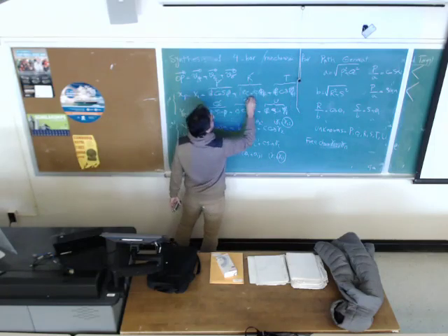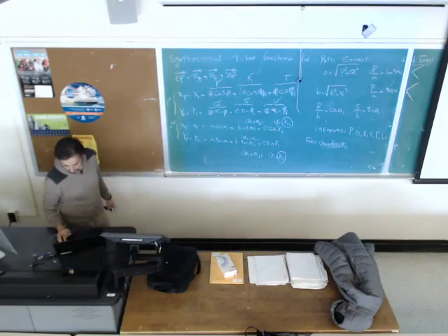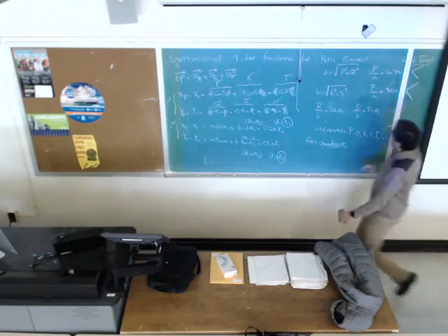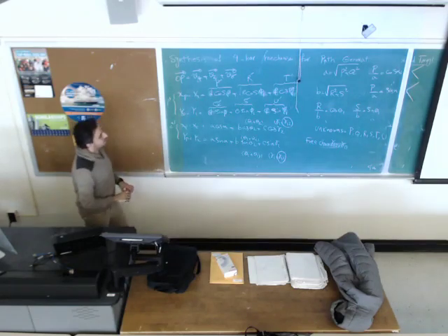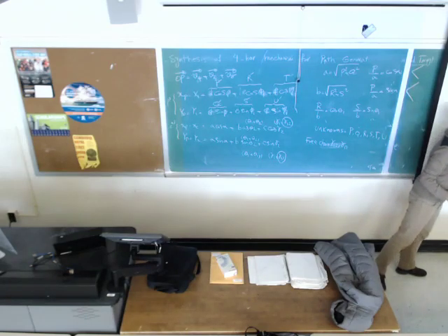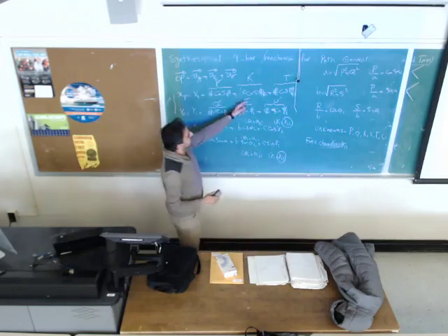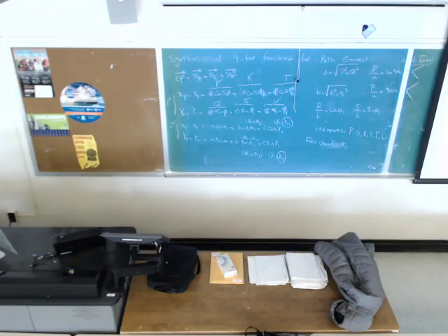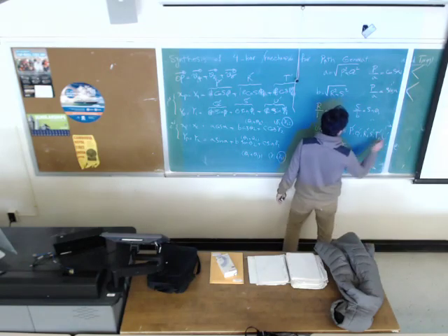P prime, Q prime, R prime, S prime, T prime, and U prime. So D cosine of beta, E cosine of phi, F cosine of eta equals to x1. Similarly for y1. For all 6 equations, for all 3 precision points, I'm going to use I instead of repeat this equation for the second and the third. And then I'm going to write all angles with respect to the first precision point. This equation is going to change to this. I replace phi by phi1 plus phi12 and eta by eta1 plus eta12. So in this equation, the unknown will be P prime, Q prime, R prime, S prime, T prime, U prime.